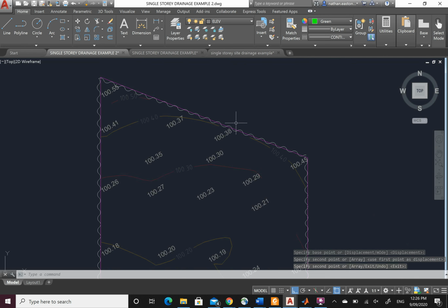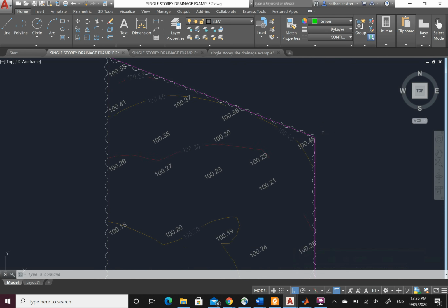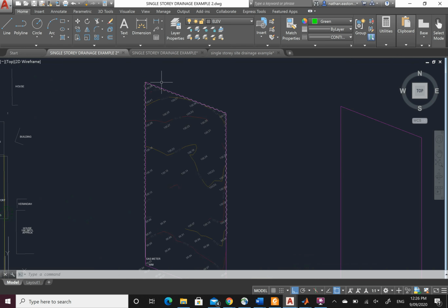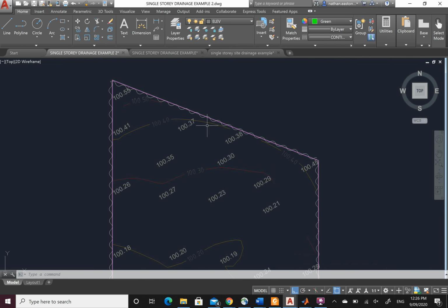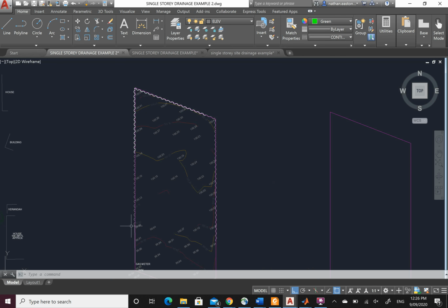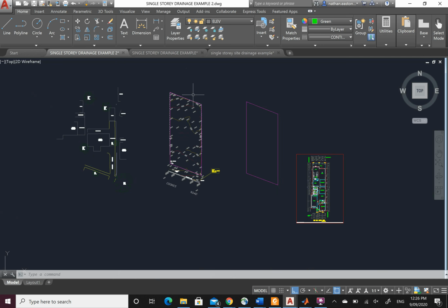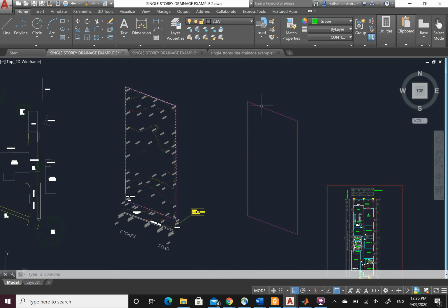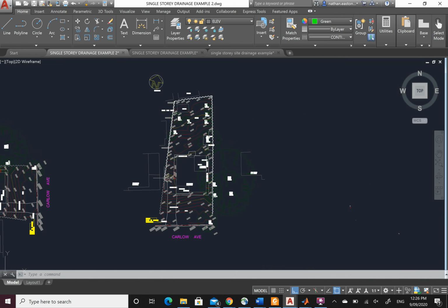Now these won't always line up and that's okay. The fence lines here are not always accurate. We have to take the land title, but we have to have like a goodness of fit. So we have to go within reason. Is that cutting through the lines? It is. Here, is it okay? Is it within our boundaries on the sides? It is. The fences here, you have to also be aware that these could be tilting, they could be falling, they could be anything. Our land title is what comes from the urban regional planners. It's always true. So we have to take this as gospel, and we've got a bit more wiggle room with the surveys.